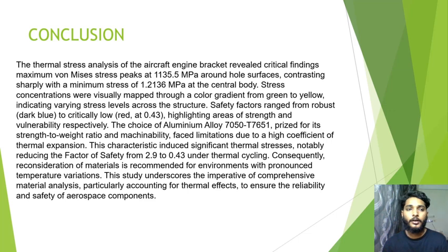Conclusion. The thermal stress analysis of the aircraft engine bracket revealed critical findings. Maximum von Mises stress peaks at 1135.5 MPa around the hole surface, contrasting sharply with the minimum stress of 1.2136 MPa at the central body.